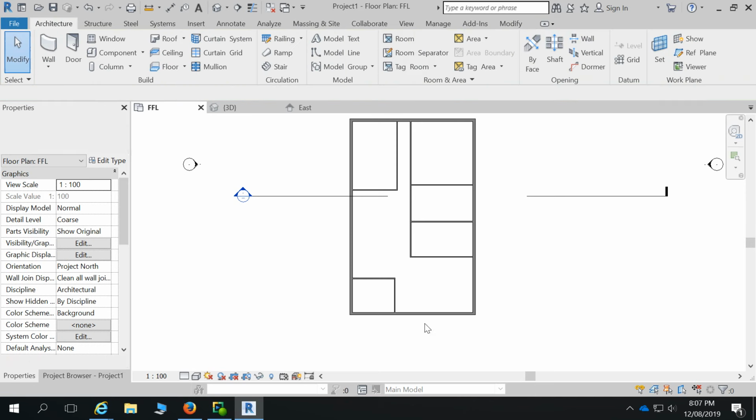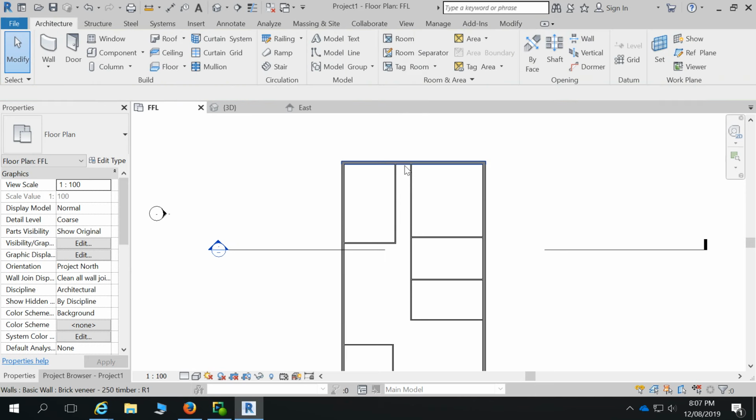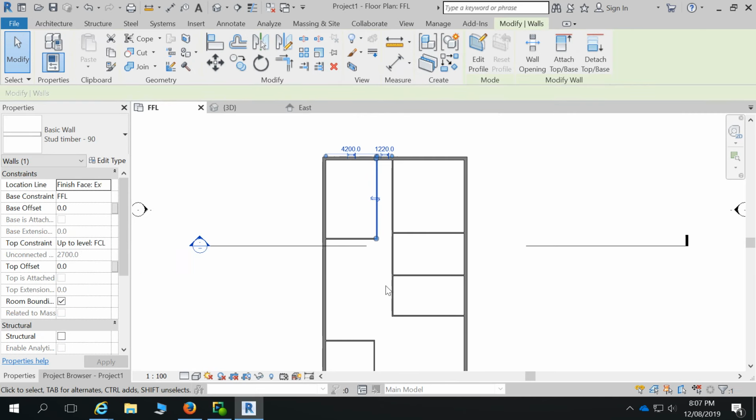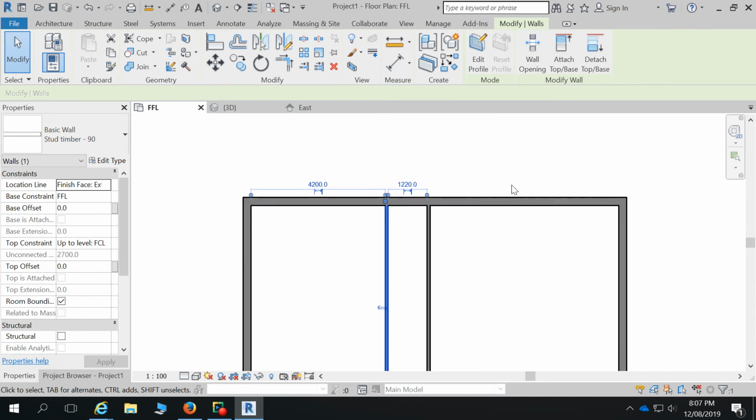So we've got a couple of different walls set up inside, but we haven't really got any dimensions or anything for these sorts of rooms or spaces or whatever. So now what I want you to do in the 2D space is just click on one of your internal walls and notice how you start to get some dimensions coming up. So these dimensions are sort of just quick dimensions that pop up randomly, and if you click on a wall, it'll give a dimension from one side of the wall to the next and the opposite side. So it's picking up on the first reference it can see.